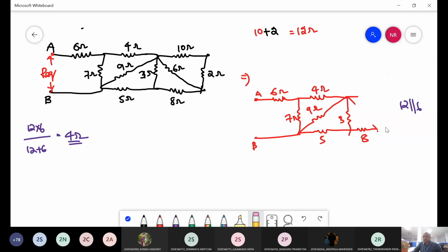see, observe the step by step. The resultant is here 4 ohms. Now next level, that is 4 and 8, that is series. 4 plus 8, that is 12 ohms. Now again I am removing these two elements and make it only here. Its value is 12 ohms.